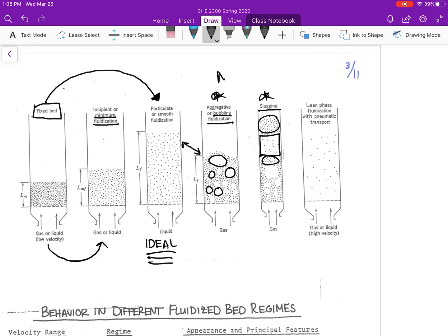Both of these are not ideal. They do not result in an even distribution of fluid. Therefore, they are not serving their main purpose here, which is to help evenly distribute the fluid by increasing its interfacial area between, in this case, the gas and the catalyst part, the packing itself. The point of our packing here is, all the time, to increase that contact area between, we'll take the water and sulfur dioxide example.